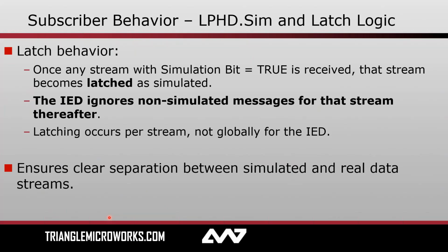That device will continue to process streams which do not have the sim flag set, and then for each of those streams, if it suddenly sees a simulated stream which replaces the real one, it will begin to ignore the real one and process the simulated one forever, even if that simulated stream goes away, until the point at which I set my LPHD Sim back to false. So it's very important that when you're done with virtual isolation testing, you take all of your devices out of simulation mode, setting LPHD Sim back to false.